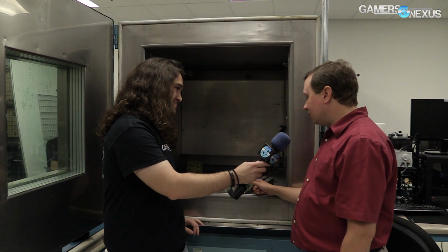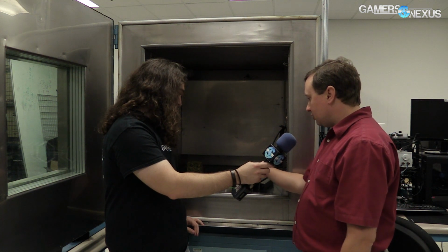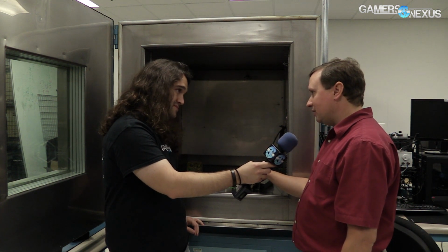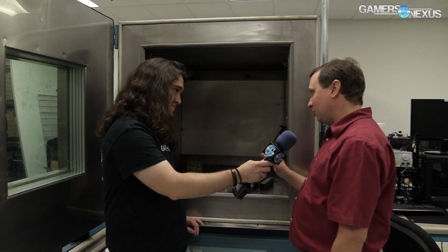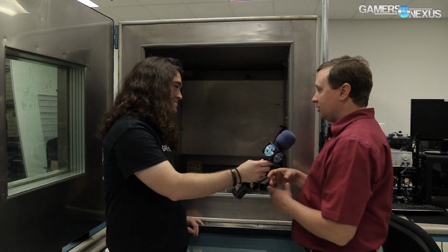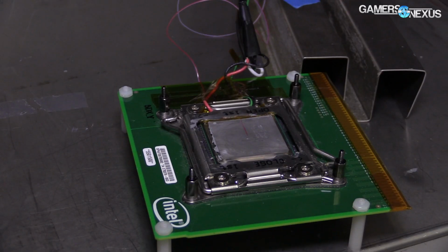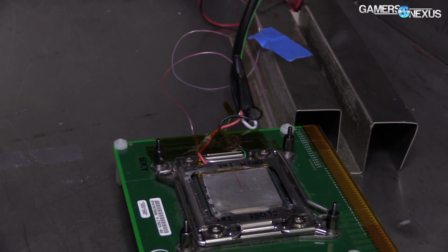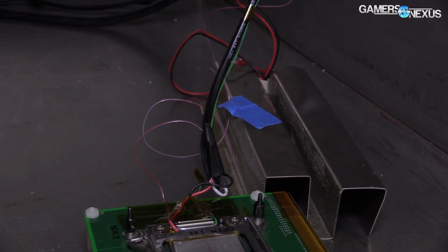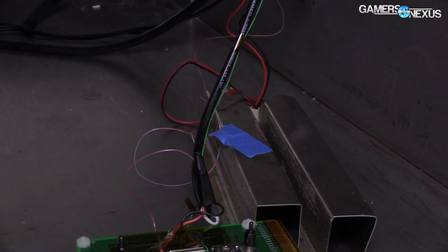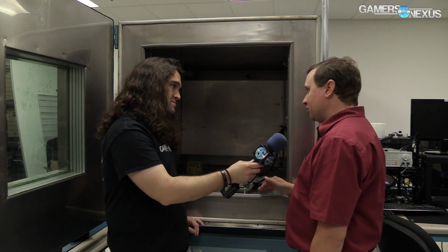All right, this is an Intel thermal test vehicle for a Socket 2011 processor. It has a Socket 2011 sized CPU device here, with a heater built into it. The heater is the same size as the microprocessor in real life, so it has the same heat flux per square millimeter as a real processor. This little line right here on top is a thermocouple that's embedded in there that allows me to measure the temperature at the very top of the package. I can measure the temperature of the heatsink, or of the ambient, and then calculate the effectiveness of the heatsink and its performance in degrees C per watt.